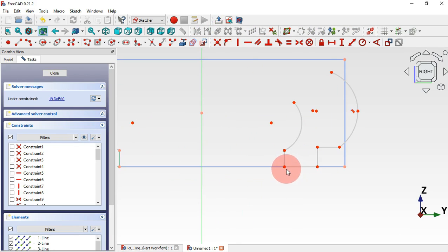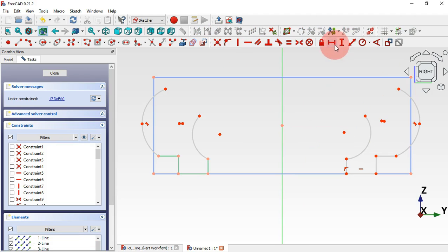And now let's drag this endpoint here to see if we have problems, and we have problems. This line here must be horizontal, and this point here we have to constrain in this edge here. Select this constraint, and we have this. First let's select the symmetrical constraint, this tool here, and now just select this endpoint and this endpoint, and now the vertical axis.